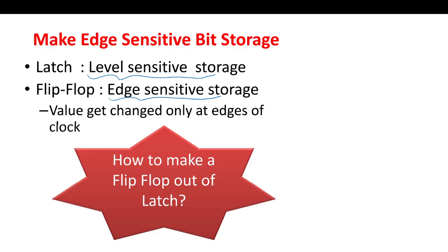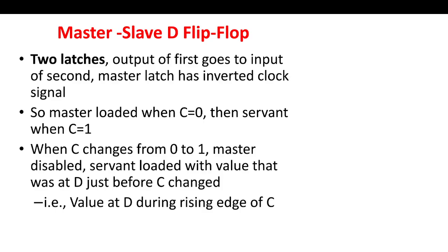Latches are transparent for the complete level, and a flip flop is opaque and operates only at the particular edge. So the value changes only at the edge of the clock.